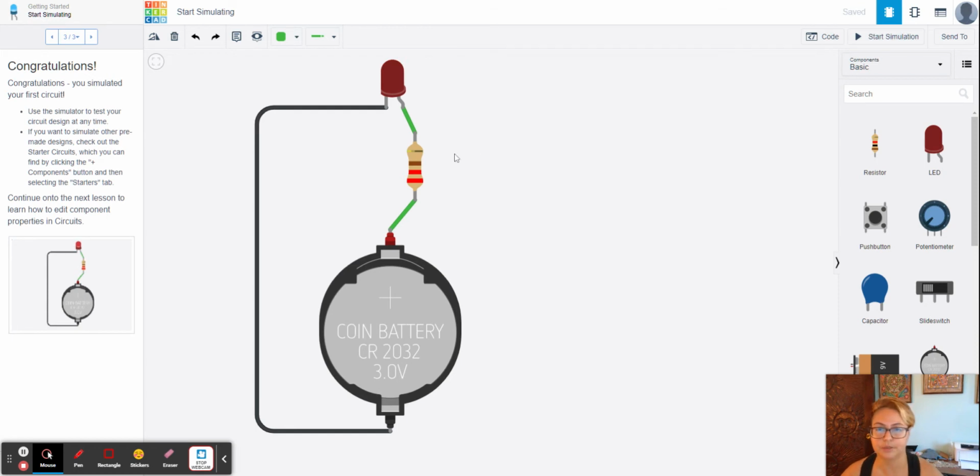Now, here are the parts. In a light emitting diode or an LED, you have a side that's called a cathode. A cathode is the negative side, okay? The anode is the positive side. You'll just have to remember that. Okay, so positive anode, negative cathode. The negative end, the cathode, of the LED light is connected to the negative end of the battery. Okay, so negative to negative.